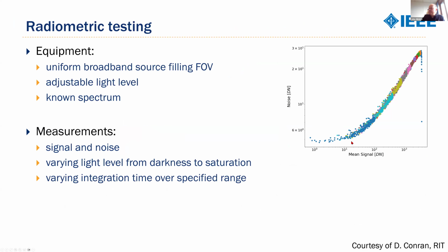In the radiometric test, you need to vary the light level and characterize the noise as a function of light level to do a photon transfer measurement, which is a very informative way of looking at things like saturation level, scaling factor to photoelectrons, readout noise, and so on.